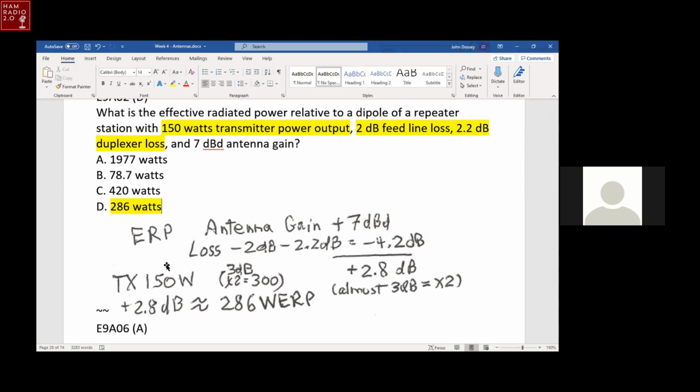Well, I learned something today, didn't I? So one of the other things that's happening is you've got a lot of reflected power going back at your radio, and your radio is probably automatically cutting the power down, even though you have it set at 100 watts. It may turn it down on its own, depending on how new a radio it is, because you don't have a balanced system.